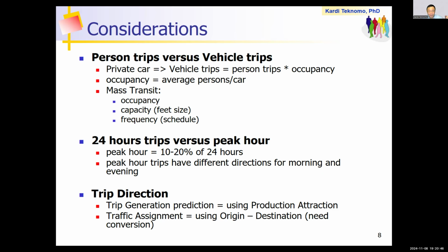And of course there is different demand based on the time of the day. If you want to design, of course you will design based on the maximum, in this case, the peak hour. So if I don't know the peak hour, but I know the average annual daily traffic, AADT, how will I get the peak hour?